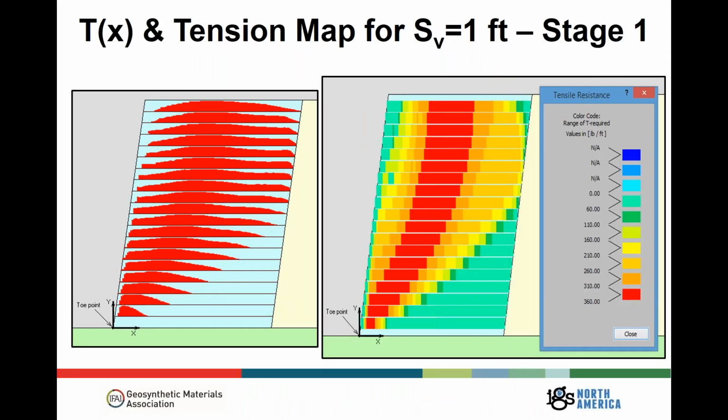Here's the tension map for the system. Now, it's still a pretty simple geometry. So we see a band or a swath of the maximum reinforcement loading lying within one region. However, the max T-max is not necessarily determined from a singular failure surface. Here, we're shedding loading also based on pullout at the rear end and then shifting for the connection demand.